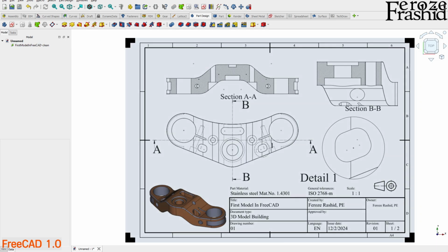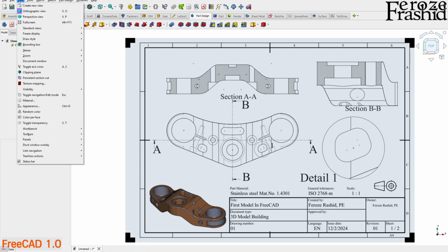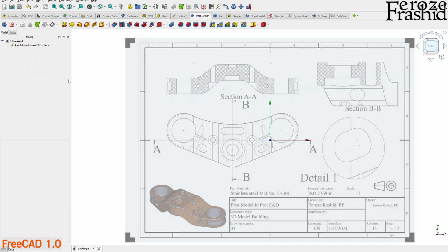While drawing this sketch, I want to match it up with this model, but we don't know where this image is as far as this three-dimensional space goes. So let's turn on the axis cross, which represents the center of the origin, like the center of the universe in this workspace. And looks like I want to set its center right here at this center point. I want to relocate the image.